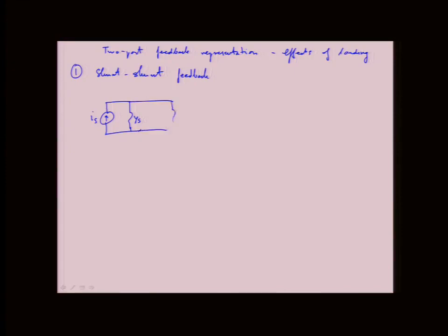So what we used to have was this goes into some amplifier with input admittance, in this case I'll just call this Y11A, and then that develops some voltage VI at the input. The amplifier I can again either write as a voltage-controlled voltage source with impedance, or I'll just write it in the Norton equivalent as Y21A times VI.